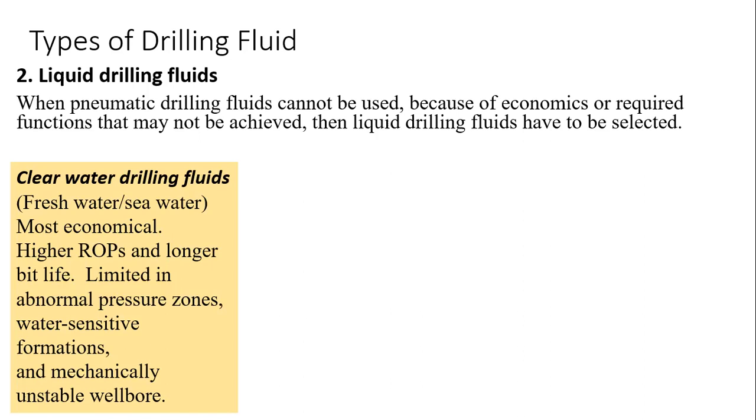And we can't use clear water during this portion. So we also say that it's disadvantageous in water-sensitive formations. There are some rocks or zones that have higher conductivity or low resistivity. When you use water, since water is conductive, it can affect your logging, the information that you are getting from these formations during the drilling process.